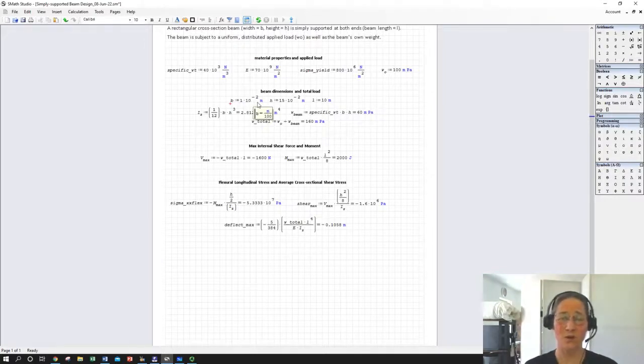And this is where your structural steel shape guides are usually great places to start. What base to height is even going to act like a beam with this loading? Chances are that would not be reasonable, and in fact we might be constrained to something more like 4 to 15, which would be a little better.